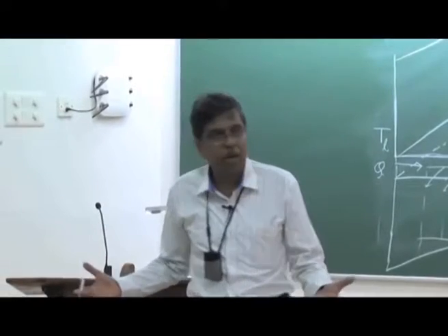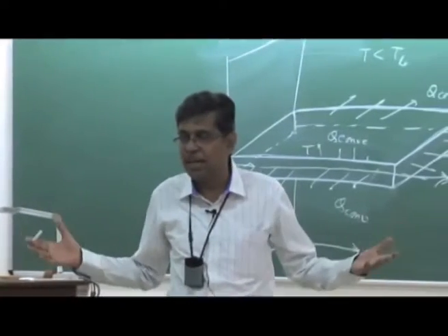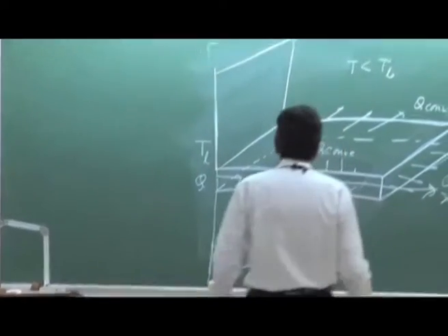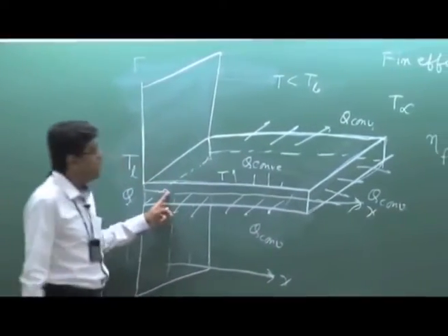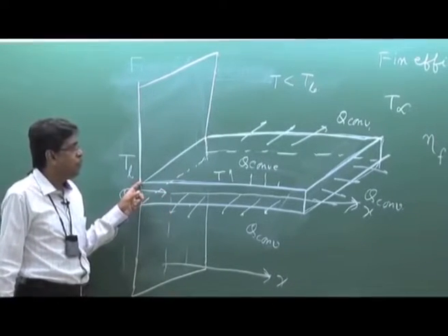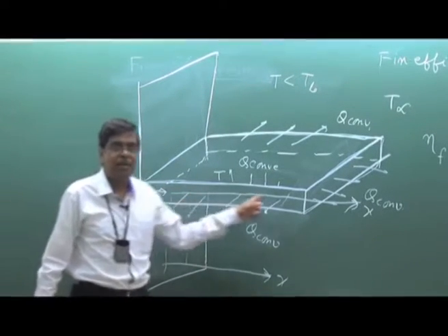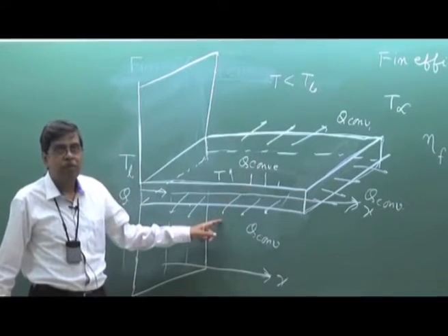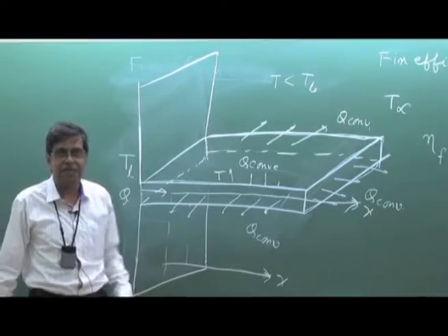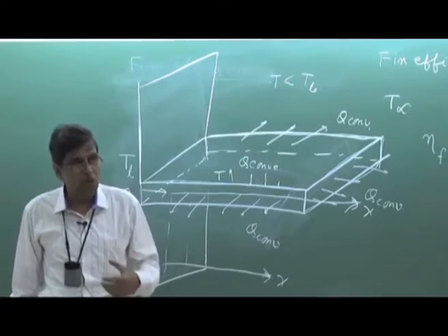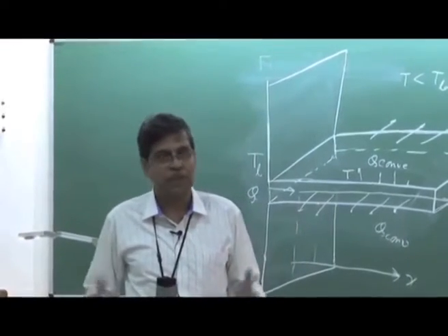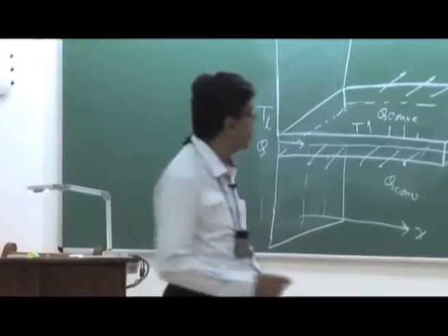If the thermal conductivity of the fin is infinitely high. Otherwise, in the actual case, the fin temperature decreases along the direction x. But at any x, this is the same for all the lateral surfaces. This we took in deriving the differential equation for temperature distribution from the energy conservation principle.